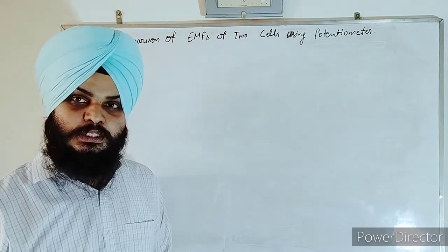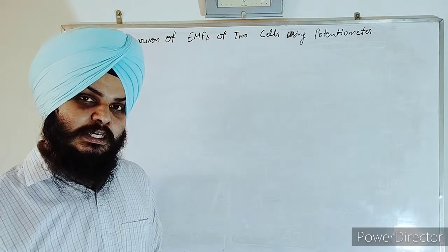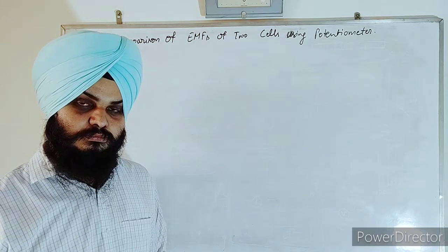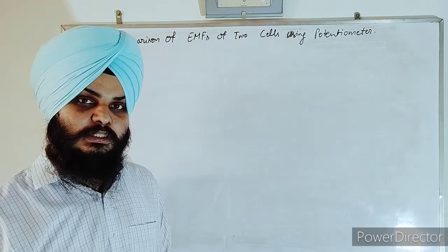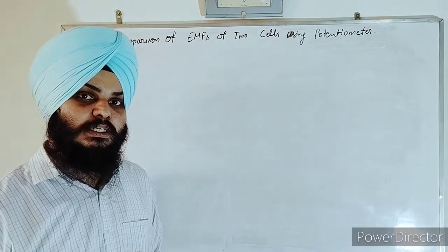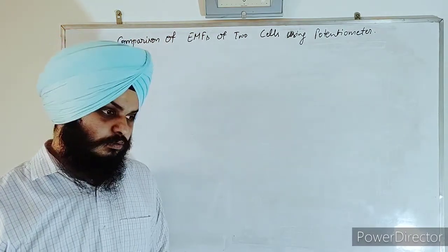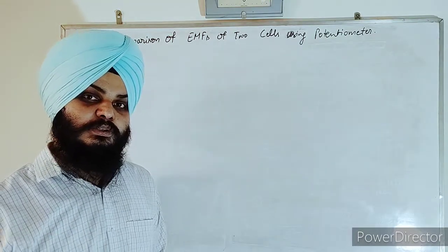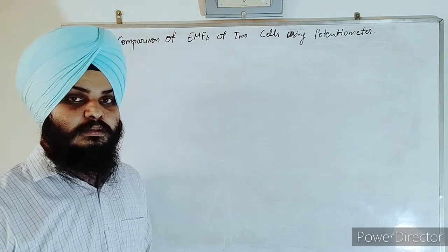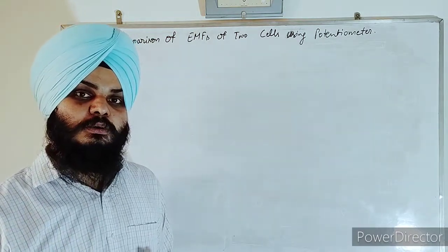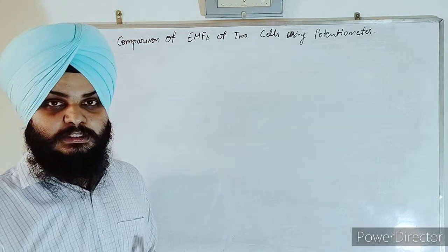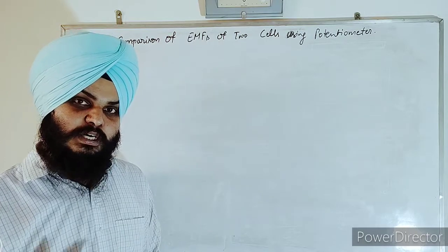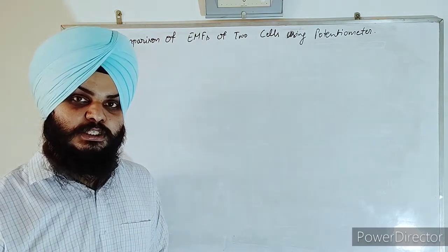So this is an obstruction in calculating the potential difference or the EMF of the cell by using the Weston-type galvanometer, because it draws some of the current from the cell. So if you start finding the value of EMF by using a Weston-type galvanometer, then that value of EMF will not be correct. We need an arrangement which takes no current from the device and provides the correct potential difference.